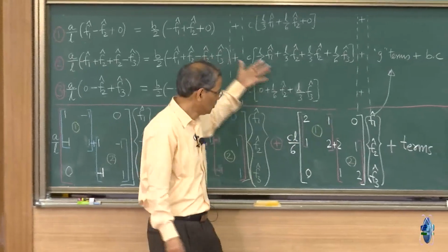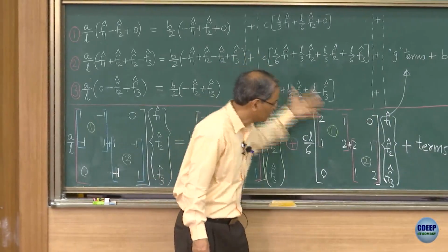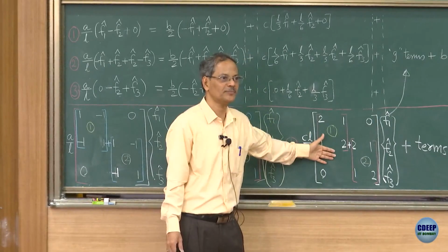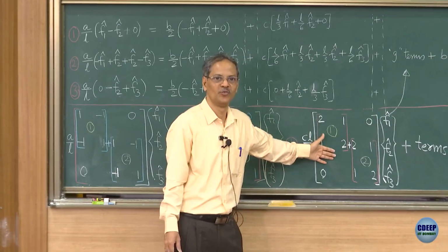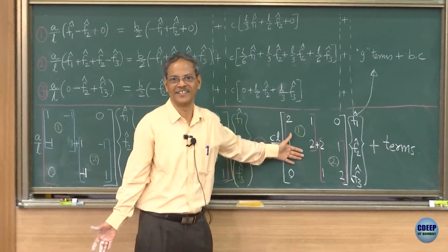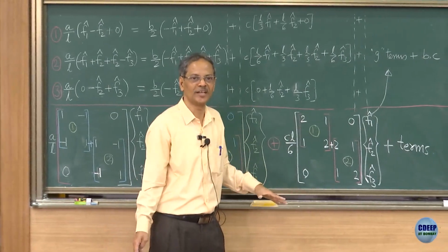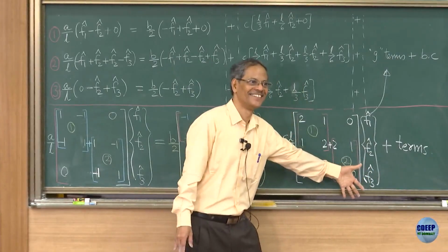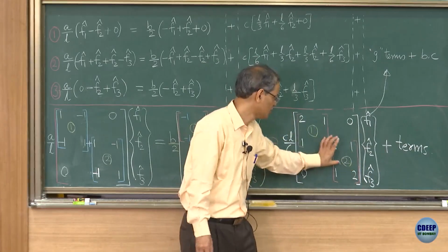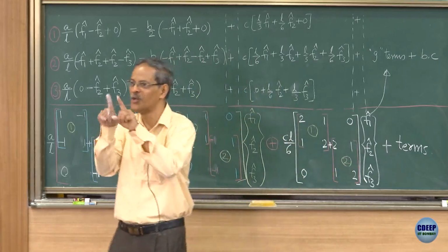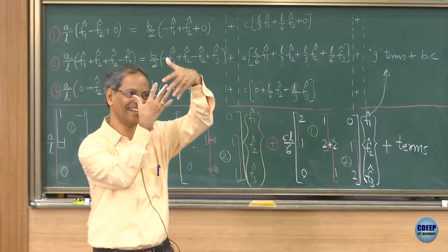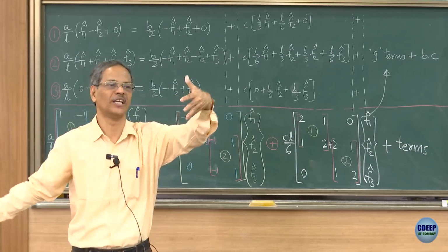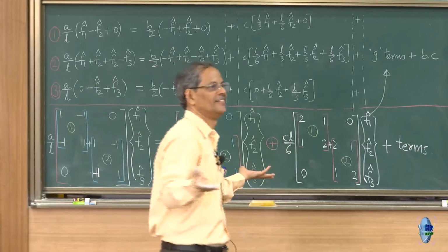and then if I were to say now 3 elements, what would be the size of this matrix? System matrix 4 by 4. And how would that third equation come? It would add to the leading diagonal one more submatrix like this, a 2 by 2 matrix; keep on adding it along the leading diagonal like this. You can have any number of elements. So, okay.